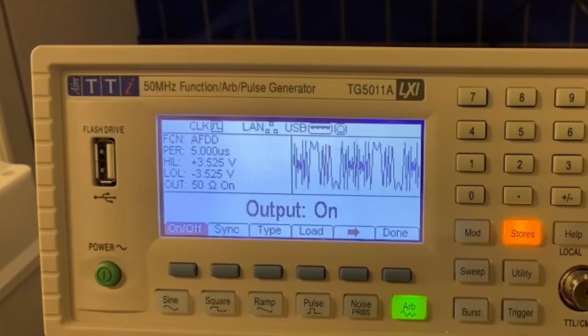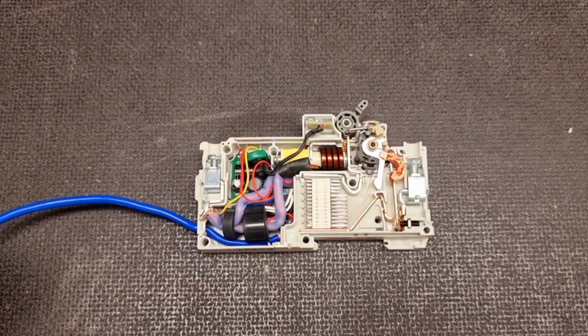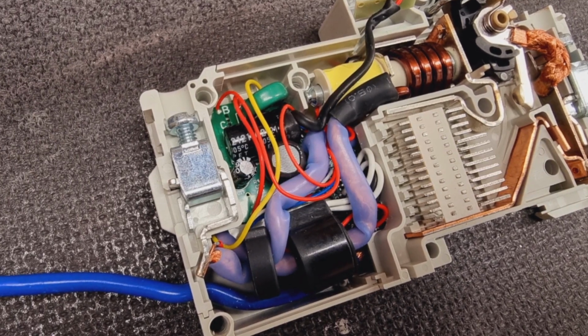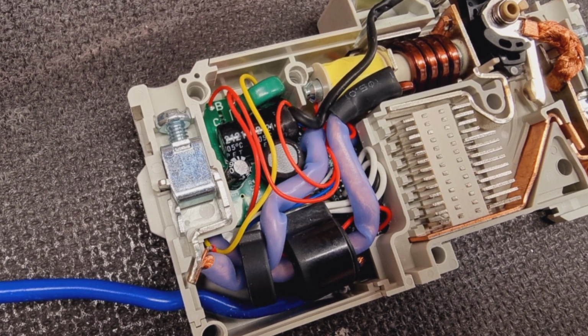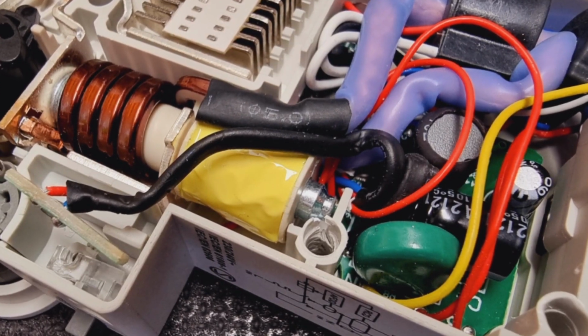And that is how an AFDD detects an arc fault occurring. It's programmed to monitor the shape of the current waveform supplying the circuit, and then trigger the disconnecting mechanism when it sees characteristics like this. Now, if we take a look inside an AFDD, we can see the components that allow this to happen. It takes protective devices to the next level by incorporating a small PCB that's been programmed to monitor and recognize those waveforms we just discussed. This then features a triggering circuit that operates the tripping mechanism and disconnects the circuit.